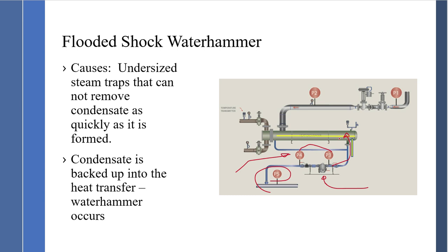And you'll get waves occurring inside the heat exchanger due to the configurations of heat exchangers, and you'll get water hammer. And it will cause tube failure, tube sheet failure, baffle failure, support failure, inside the heat transfer plate and frames, gasket failure, gasket material failure. Just causes a lot of issues.